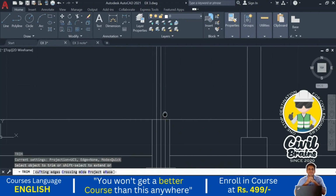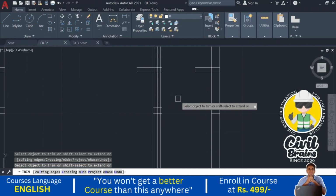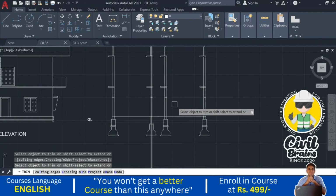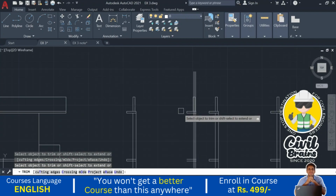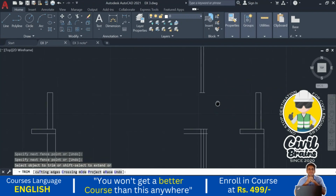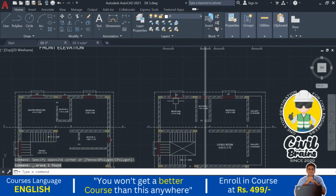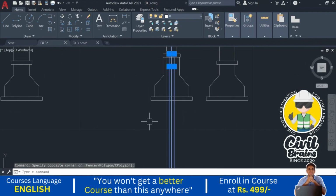Just trim. Okay, this is the lintel level, this is the slab level, and again we come to this one here, next plan, that is also the partition wall. So again the same thing, and this is the slab level, and in the intermediate there is no parapet, only at the corners or only at the end of the walls we need to provide the parapets. So just delete this one.